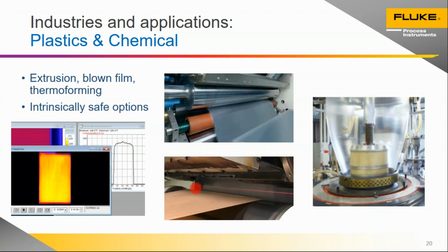And what's pretty difficult to do with many wavelengths, but can be done quite well, as explained by Adam on that one slide, using the right wavelength, and we do have scanners in, say, a 3.4 micron format, that scanner would actually read not through this and look at the background temperature of whatever's behind it, but actually look at the surface temperature of that thin material even without peering through it. And again, that same wavelength is commonly used in, say, a blown film application.